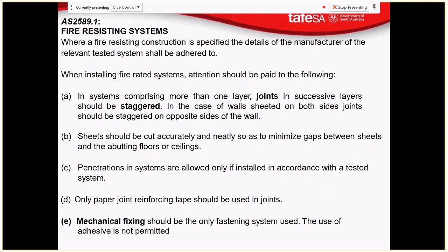So what we have, and what we've mentioned before, when we build buildings close together or adjoining, we need to have them separated by a firewall. Now, one very easy way of making a firewall is to make it out of solid masonry. So we can just use concrete blocks or bricks or something, ensure all the gaps are correctly filled and carry that wall to the underside of the roof covering, and we have a firewall. But masonry walls are expensive and they're also heavy.